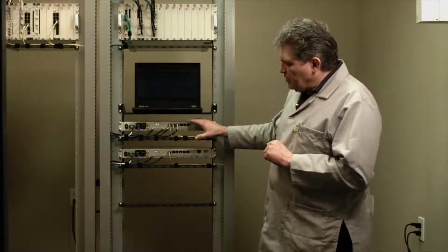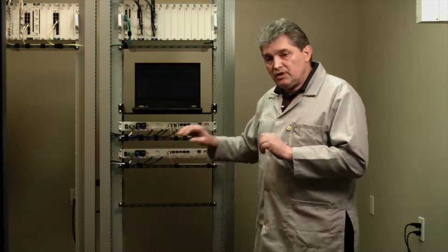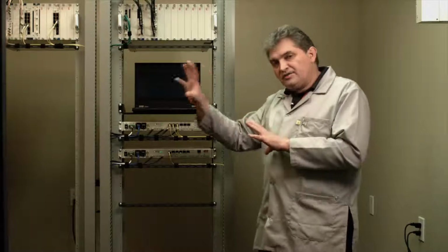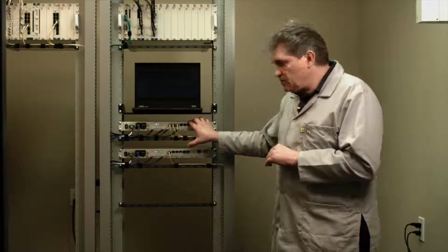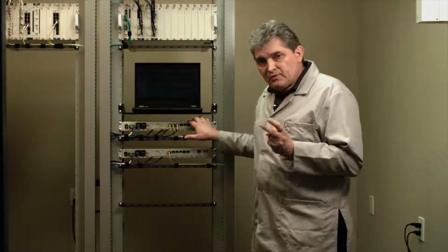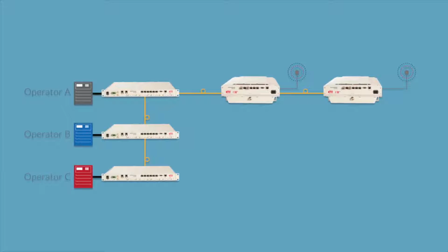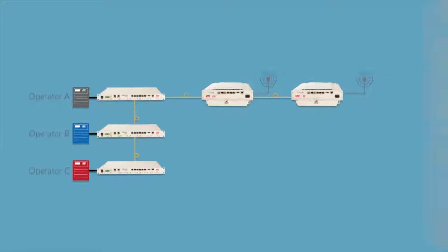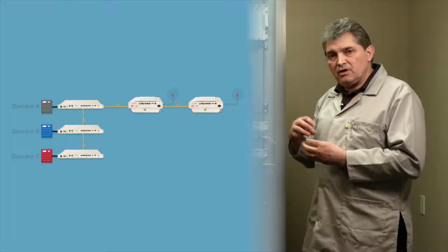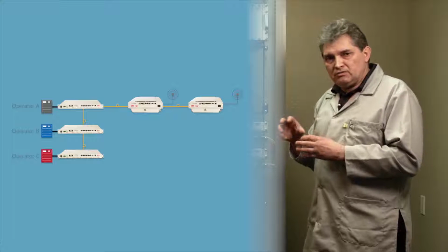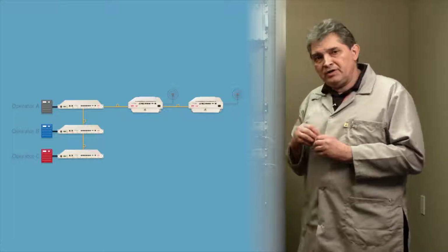The host units can also be daisy-chained, or cascaded. So besides cascading remotes, we also have the capability to cascade the host units. There are two purposes for this cascading. First one is adding an additional band or adding additional operators, where each operator has a dedicated host unit. By cascading them, we are aggregating RF signals, but this time at a digital level. And in that way, we are avoiding PIM problems.